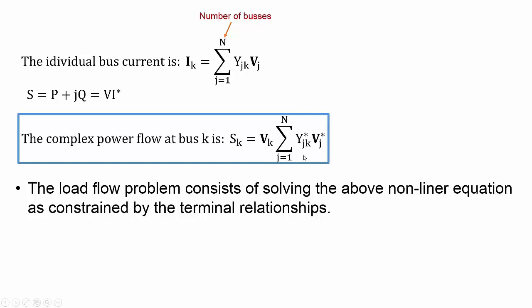However, while in theory, if we know the bus voltages, we can calculate the power flow in the branches, in practice that doesn't work because we cannot calculate the power flow unless we know the power losses. The power losses in the branches are unknown.